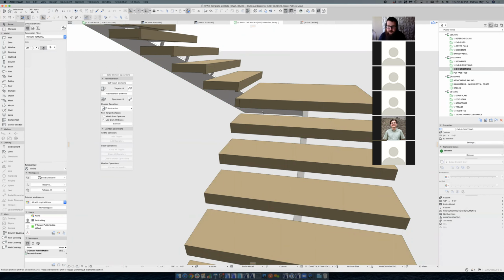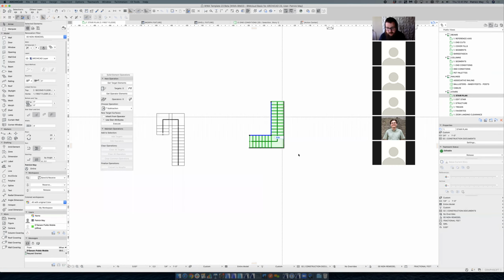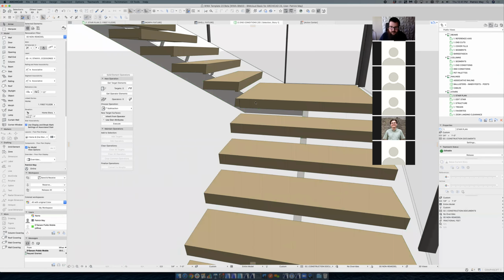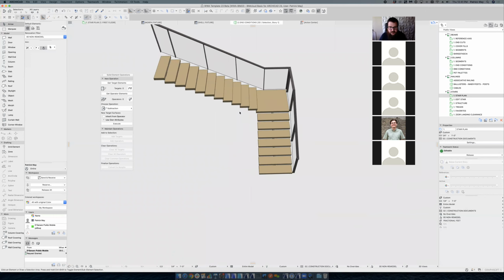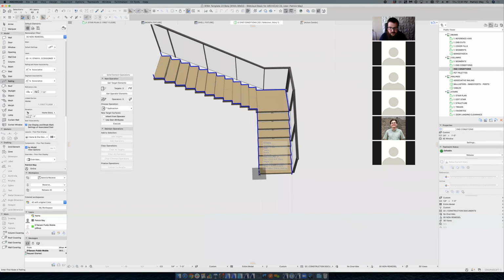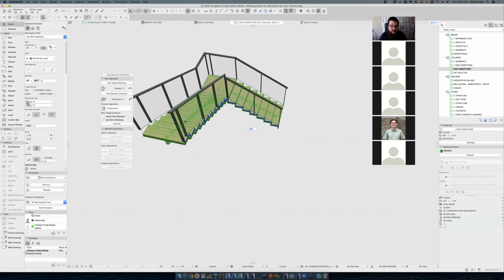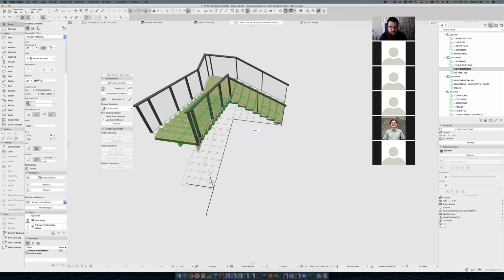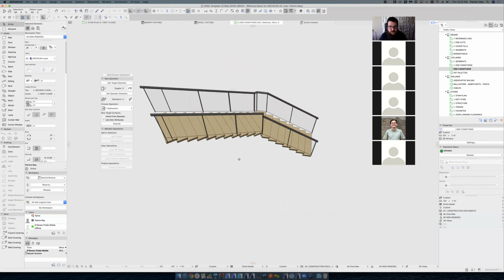The other thing about that stair and the railing, if we isolate these out together, is that if you draw the railing in, so if I hover over this stair, it'll highlight the stair. Each one of these clicks is basically saying that railing is going to be associated with that stair, which makes the railing tool kind of a cool tool, so that if the stair changes, that railing should change with that stair.